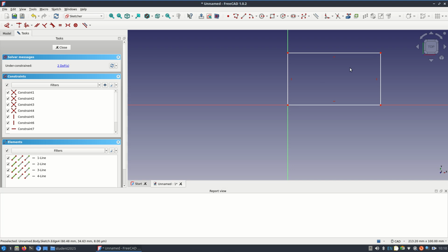If we put the home on the bottom left of the CNC, the piece is actually going to go towards the outside of the CNC. So that's why we put it here. So I know that whenever I put my end mill here to zero it, it's going to cut up and to the right into the CNC board there.